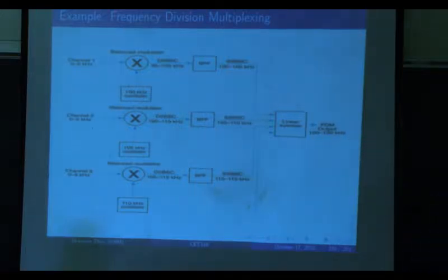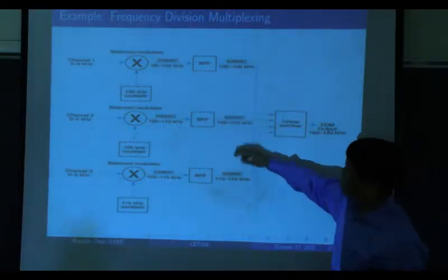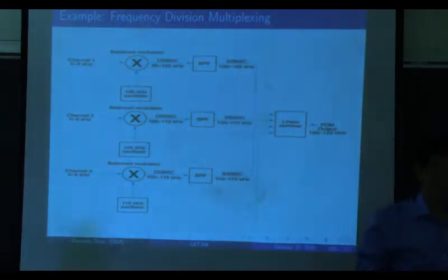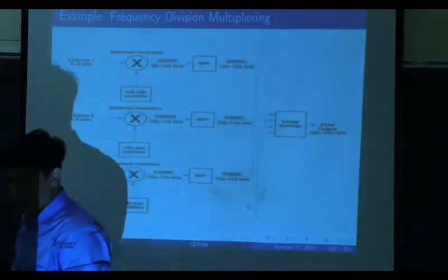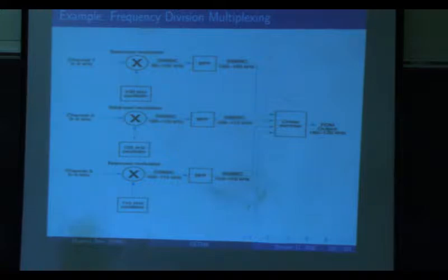It's shared in frequency. Then once we receive this signal, what to do? How to do this? What's next? Band pass filter, right? You band pass filter, you get each one, then use a demodulator to get the baseband, followed by a low pass filter to get this one. Okay, questions on this? Everything good?